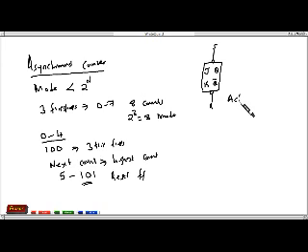This is what we call the active low reset and set pins of the JK flip-flop. So what we do is generate an output out of 101 whose overall effect is to give us a 0 that is able to reset the flip-flop, because the flip-flop is reset by an active low input.